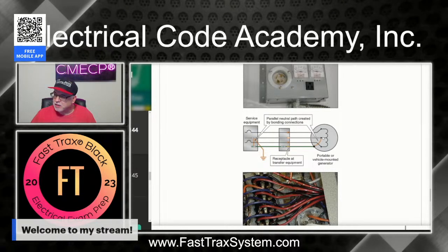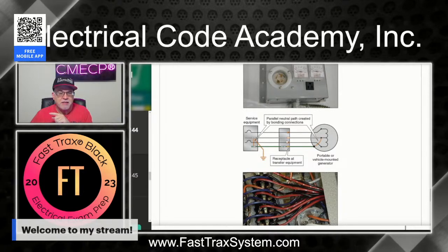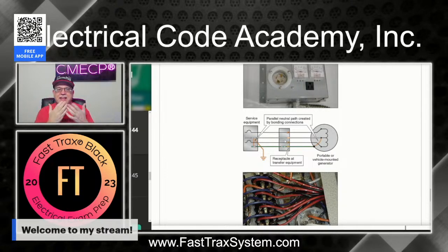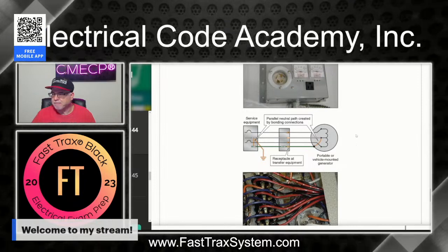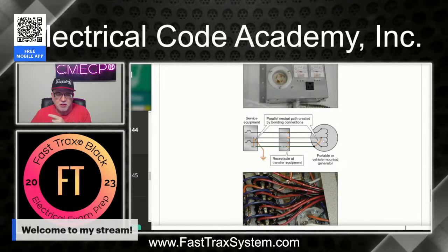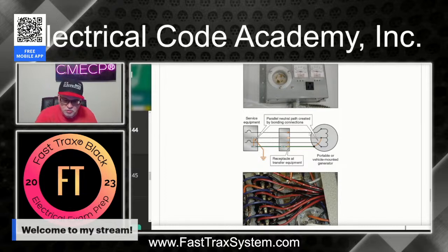But if you're going to connect it over here, and this creates a separately derived system, then you need to switch the neutral. Okay? You need to break that cycle of paralleling the neutral like that and creating that circulating current. It's all going to hinge mainly on your transfer equipment. So, that doesn't mean I can't use a generator like this, but I have to make sure that my transfer equipment accommodates that. Okay? All right, folks, let's bring it back to me.